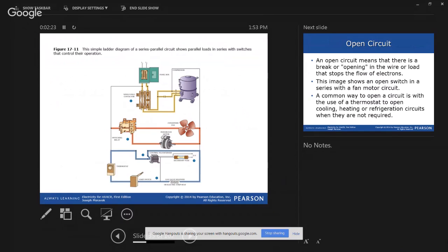Yeah, I guess you could call the thermostat and the limit switch. Those are definitely in series there. And they're getting fed by the low voltage side of their transformer, I would assume. Maybe not. I bet that's the high voltage side, because it is hooking on to the high voltage wire there.